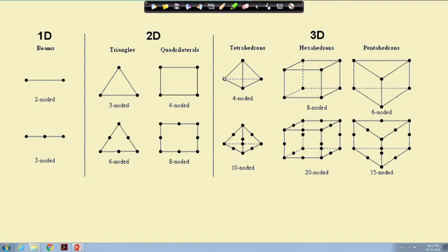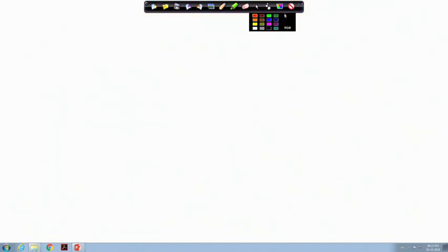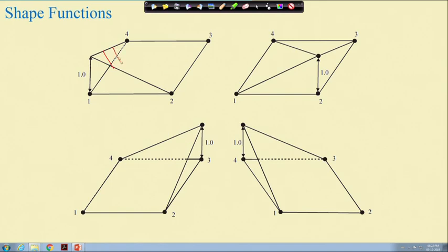Now, let us quickly see the shape of the shape functions. So, this is 1 and at all the other places it is 0. The shape function is not linear, it is actually bilinear: linear in x and linear in y both. So, this is for n1, this is for n2, this is for n3 and finally, this is for n4.